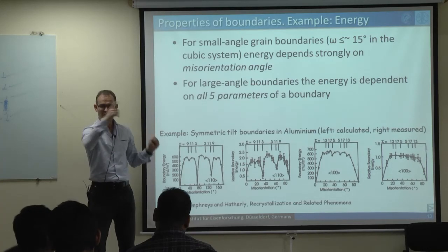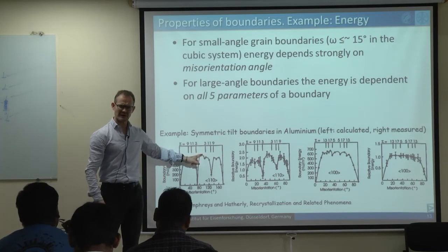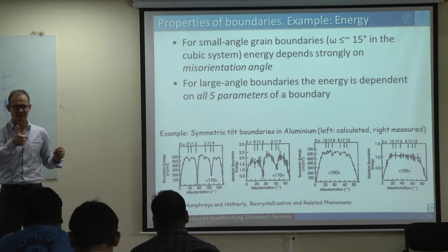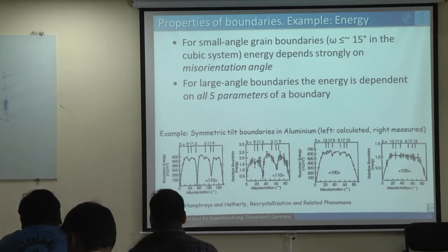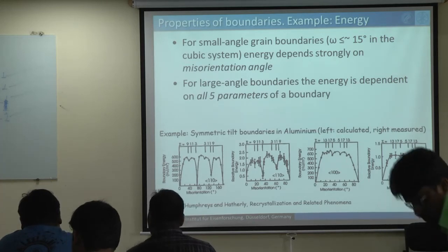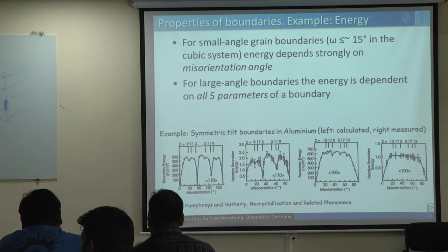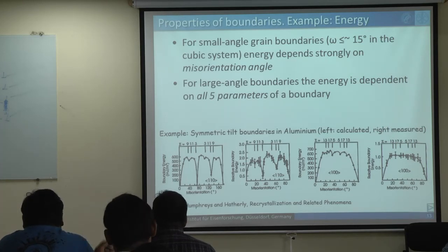And then you are in one of these non-coherent twin boundaries, and that's the sigma 3. Why do we come to another twin? Actually, the reason is, I said sigma 3 is one well-defined misorientation, 60 degree around 111, but 60 degree around 111 is the same as 70 degree around 110. And that is the same as, I don't know it, 120 degree or 86 degree around another axis.